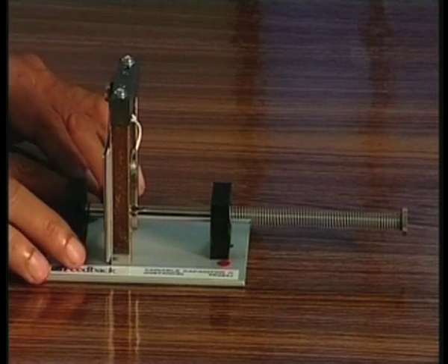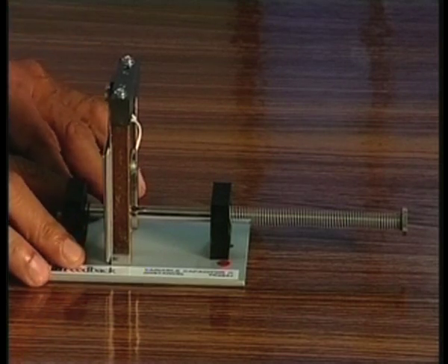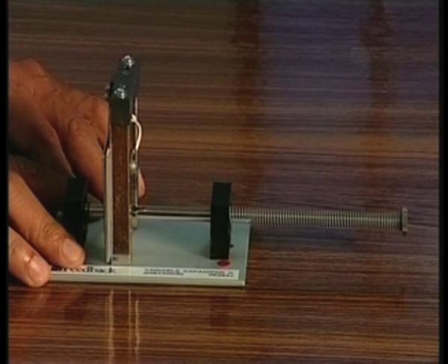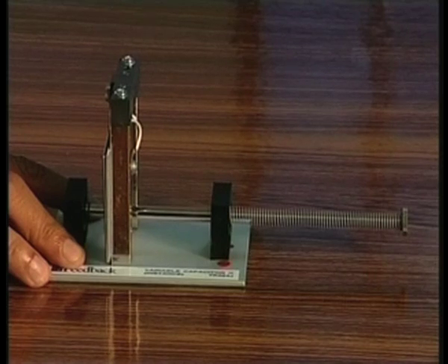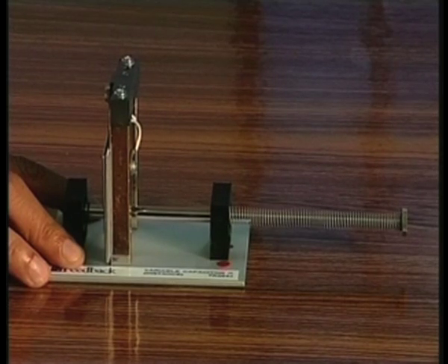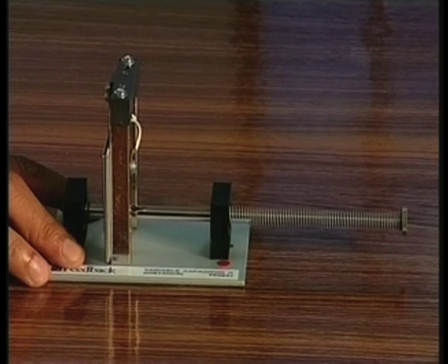This is another application of the capacitance sensor which can be utilized to measure displacement. Usually capacitance sensors are based on three different criteria. One, you can vary the area of the plates; you can vary the displacement between the plates, that means the separation of the plates; and also you can vary the position of the dielectric medium inside the capacitor. The particular gauge which you are looking at now basically depends on the displacement.